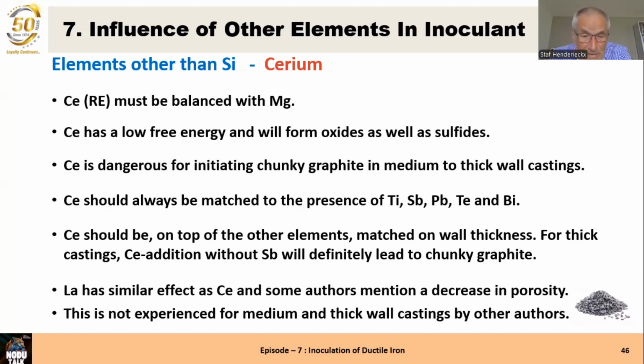Lanthanum is a little bit better than cerium, as we have seen. And some authors mention also that there is a decrease in porosity. But that's in medium and thick wall castings. I have never seen it. And some other authors say in medium and thick wall castings, it has no better effect than cerium. But that's something very personal.